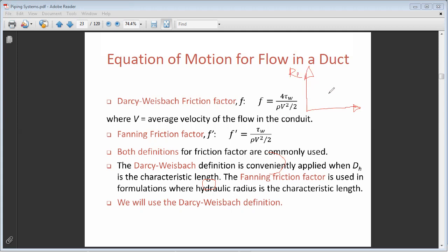Right. And we have roughness. If you have a rough pipe you can define another parameter, epsilon over d, a dimensionless parameter. We always work with dimensionless parameters. Why? To generalize the analysis. For example, Reynolds is rho v d over mu. If you check the units of all the parameters, you will see that rho v d over mu has no units.